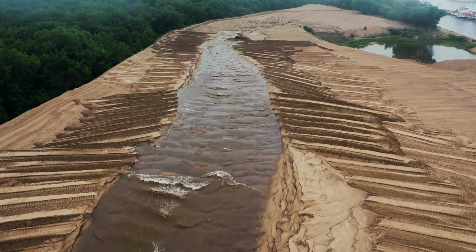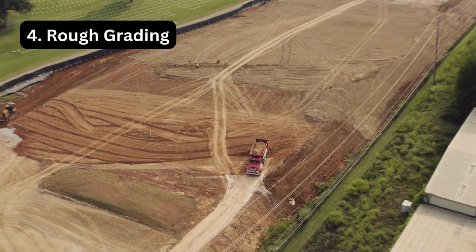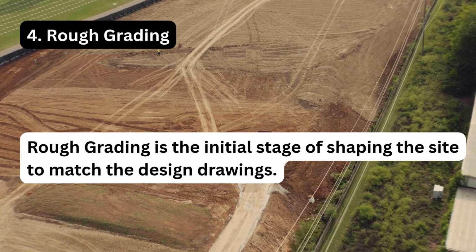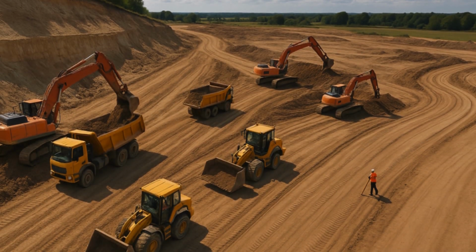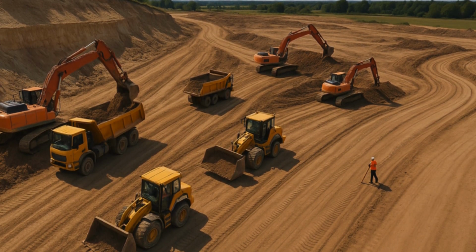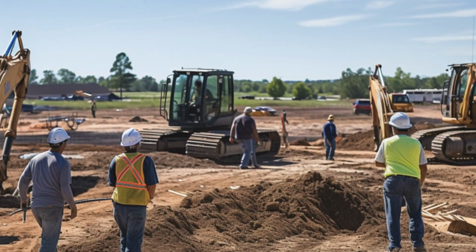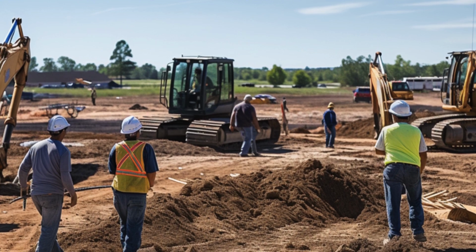4. Rough grading. Rough grading is the initial stage of shaping the site to match the design drawings. It's done using heavy machines like bulldozers and excavators to roughly reach the desired contour. This step does not require extreme precision, but sets the base for the next stage. It's suitable for preparing large areas quickly, especially in infrastructure projects.